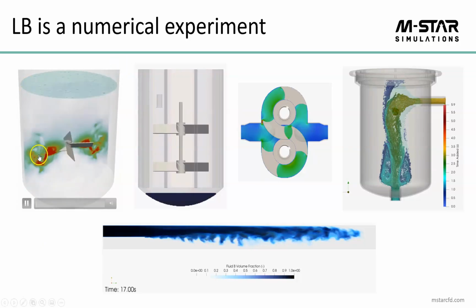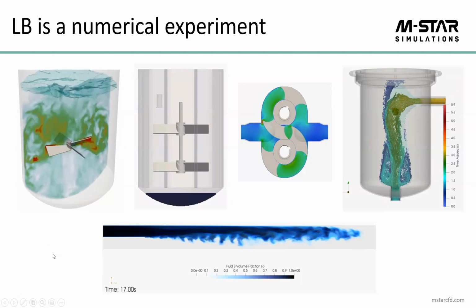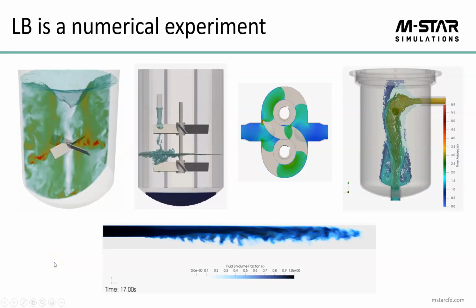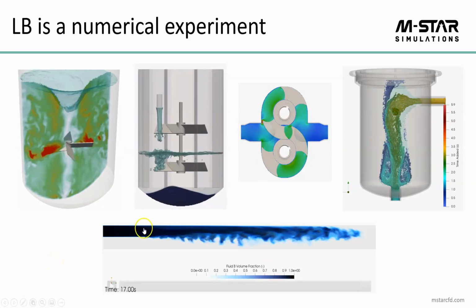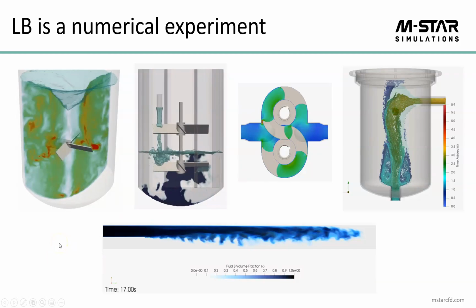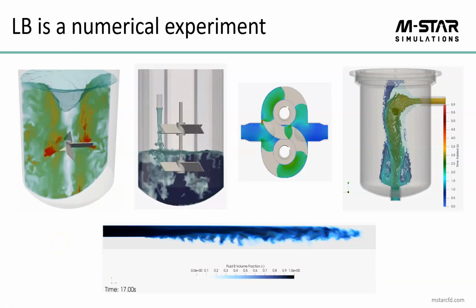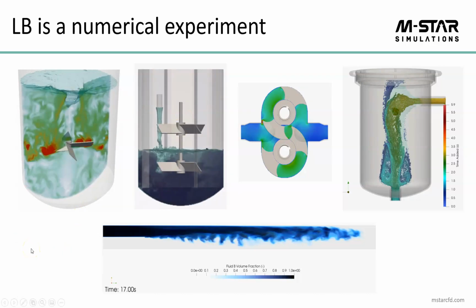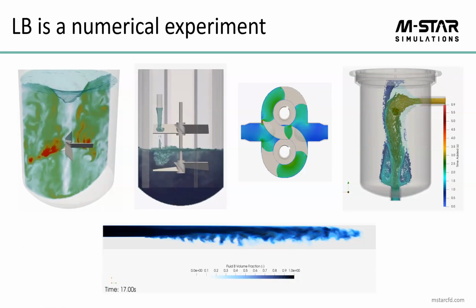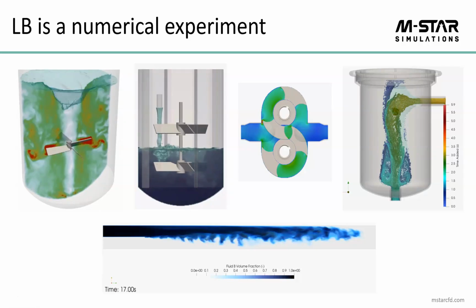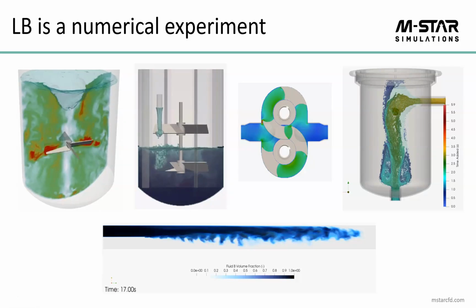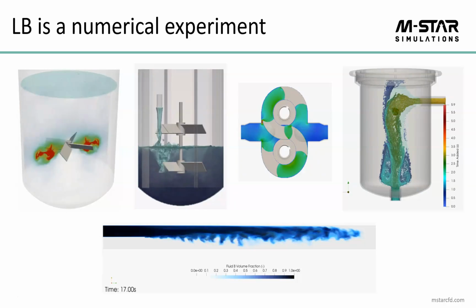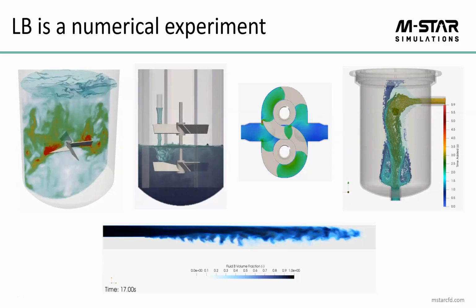And here I'm colorizing one slice through this tank per velocity, as it were, and showing the free surface somewhat transparent. Here I'm adding fluid to a slowly spinning agitated tank, causing this secondary miscible fluid to become dispersed due to the agitation and whatnot. And the salient point is that these physics, particularly the one I just clicked on, it is not appropriate to describe using a mean flow field. You need the time-dependent three-dimensional physics to resolve this complex mixing process. And that's where these novel approaches, particularly Lattice Boltzmann and GPUs, come to bear: they allow us to move away from pictures into process simulations.